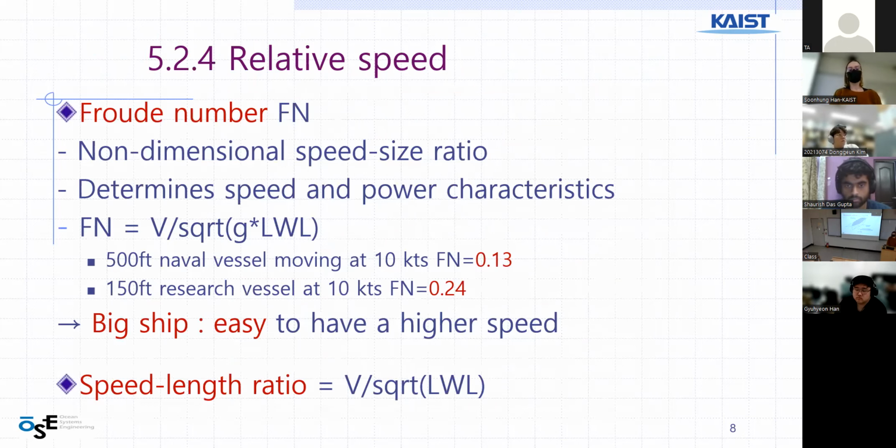So these were all coefficients that we used to design a ship, but we also use other non-dimensional numbers, like the Froude number. This number was originally created by William Froude, who defined it in his Law of Comparison in 1868. And then later, the naval constructor Frederick Weightman transformed it into the dimensionless number as we know it. So it is used to determine the resistance of a partially submerged object moving through water. In our case, it would be the ship.